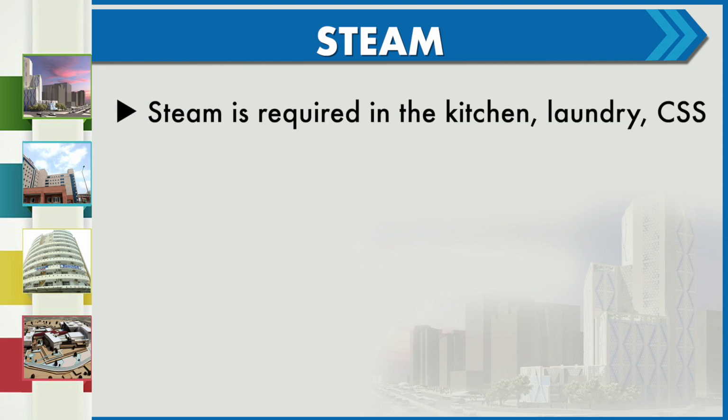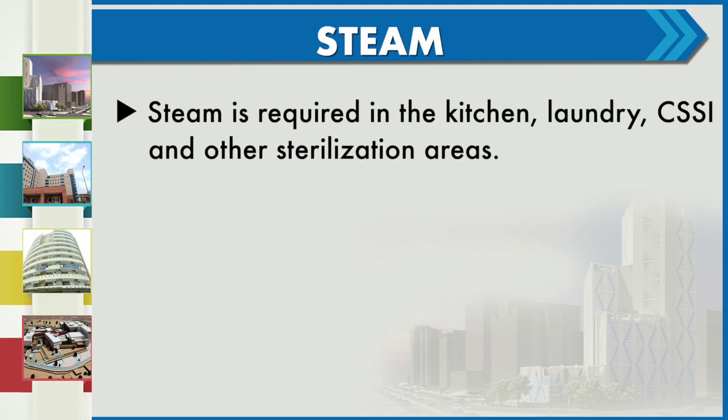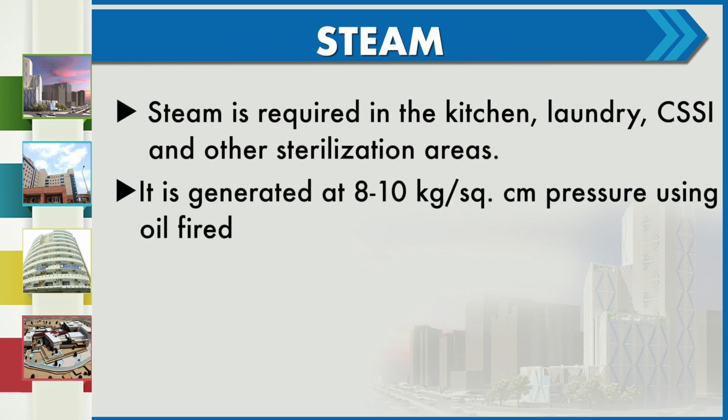Steam. It is one of the necessary requirements in kitchen, laundry, CSSD and other sterilization areas. It is generated at a pressure of 8 to 10 kg per square centimeter with the use of oil-fired steam boilers.